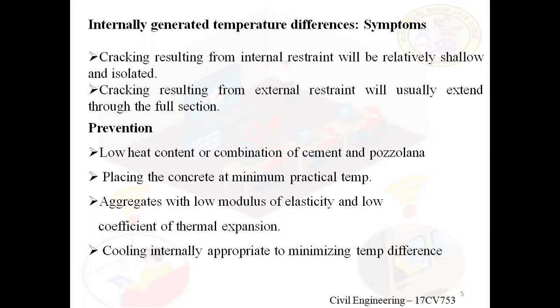The second one is cracking resulting from external restraint, which will usually extend through the full section. That means if the temperature variations affect the structural elements, the cracks will develop throughout the entire section of the element. So by this we can observe whether the cracks develop due to internal or external causes.